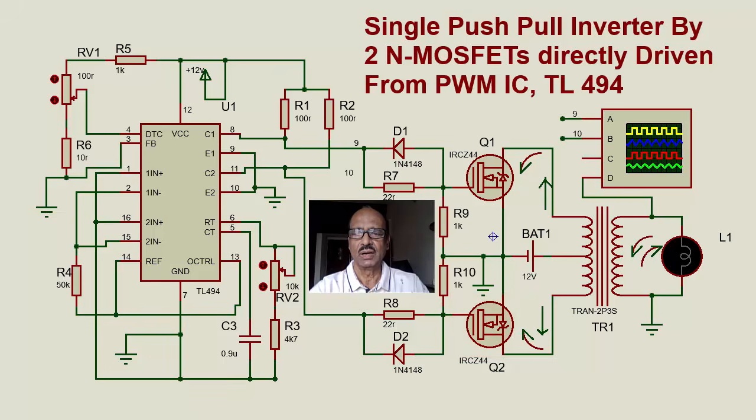Now, the arrangement which has been done here with a diode is because, while it charges the capacitor, the discharge path also has to follow through this resistor. In the process, there will be some amount of delay. To avoid that, we provide a diode here so that the discharge will take place through this, because by the time, the collector would have gone to ground.